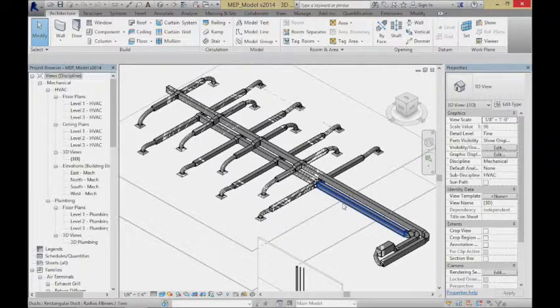These sorts of systems are actually the ones that give us the most control because we're being incredibly precise about exactly where we're pulling air and how much we're pulling. We're controlling very carefully just exactly how the air is being routed through the system. The problem with this is that I have to find a space for all that ducting on the return. And if I don't have much space, that could be a problem.